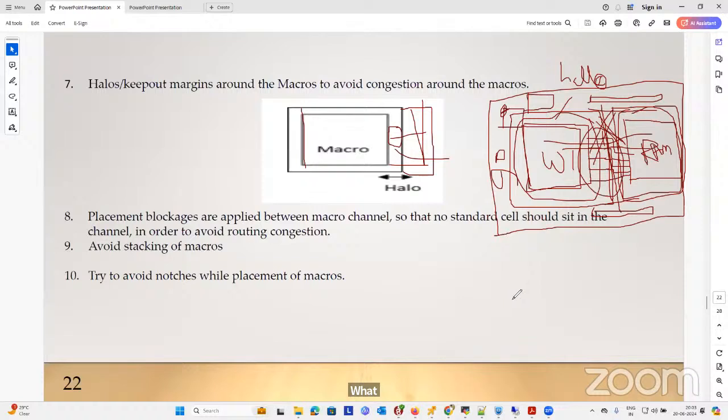Next, what is the use of standard cells? Whatever gate level netlist we get from synthesis consists of standard cells like NAND gates, flip flops, all these things. The synthesized netlist will have gates. Those gates are called standard cells, which are technology mapped and technology optimized standard cells. Clear, Rohit?